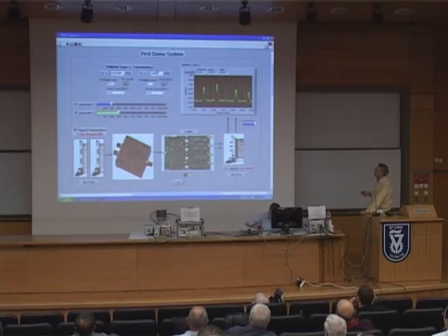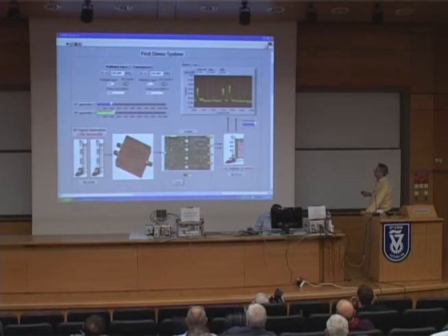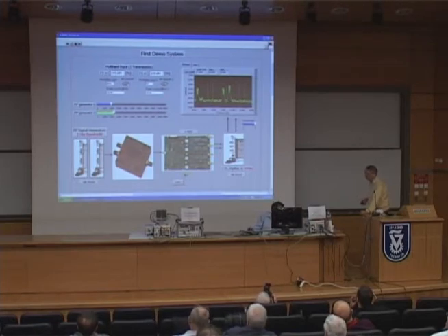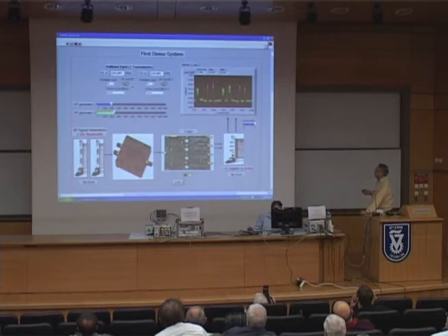This is an FFT signal. If you move this one, even a very small move here for the 200 megahertz signal went here, because this is a 30 megahertz live signal. And if you change the modulation of this first signal to FM, you see that the modulation really doesn't matter to the converter. It gives the content of the signal through.